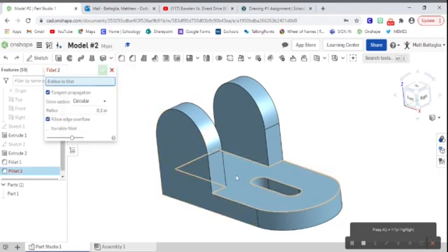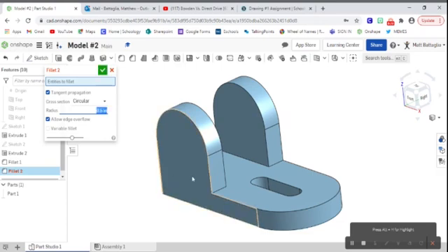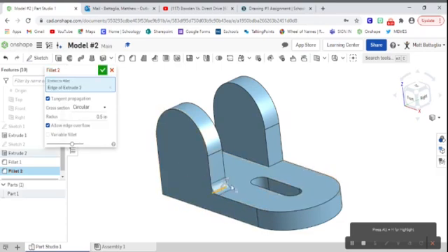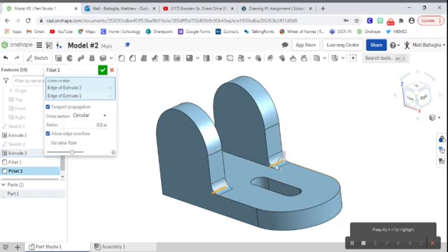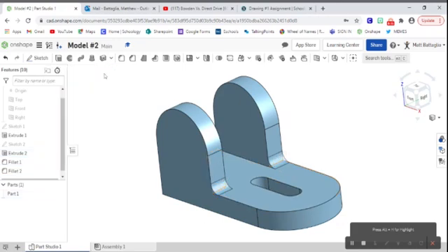The next fillet is down below here. Now, these are much, much smaller. In fact, these have a radius of 0.5. So I'll adjust that to 0.5. Once again, I'll hit my edge, and I'll hit my edge, and that'll create that nice little round over that we're looking for. Great. The only thing that we need to do now is add our holes that go directly through both of these side pieces.